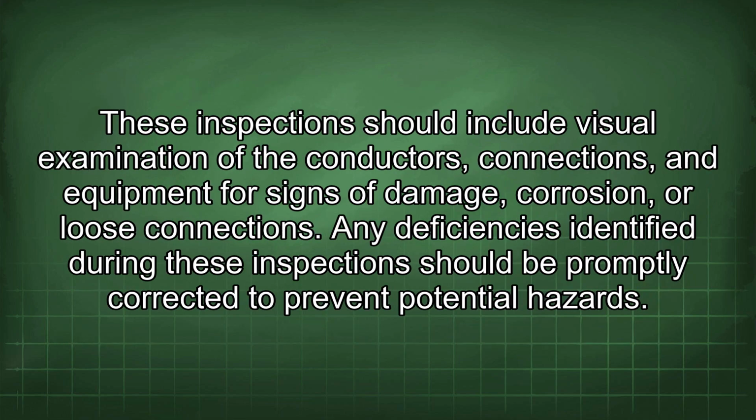These inspections should include visual examination of the conductors, connections, and equipment for signs of damage, corrosion, or loose connections. Any deficiencies identified during these inspections should be promptly corrected to prevent potential hazards.